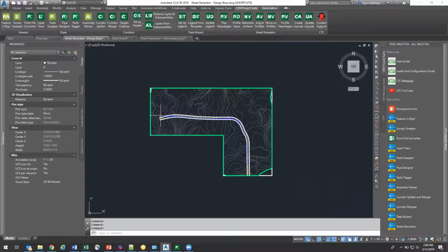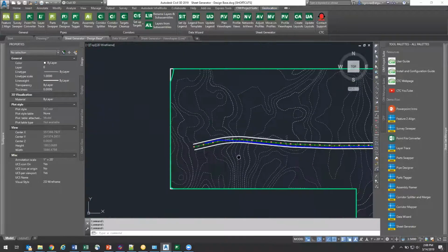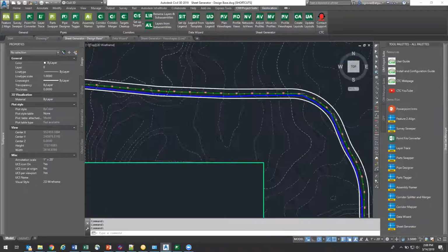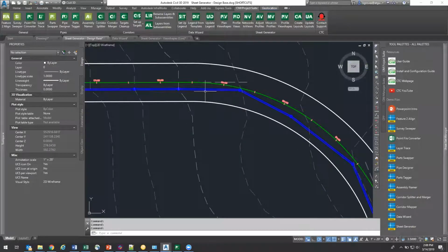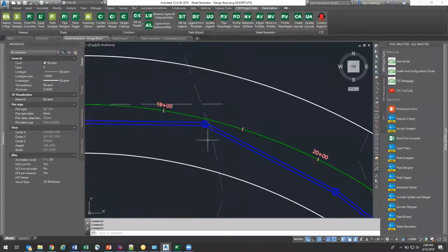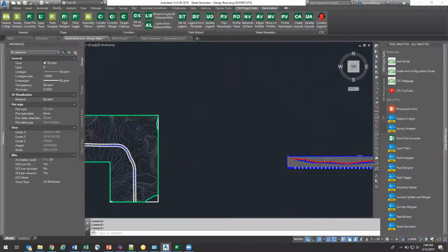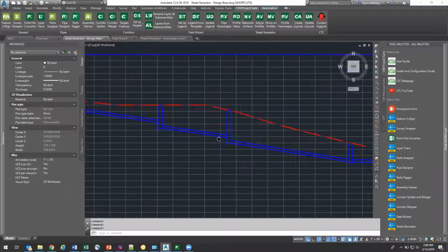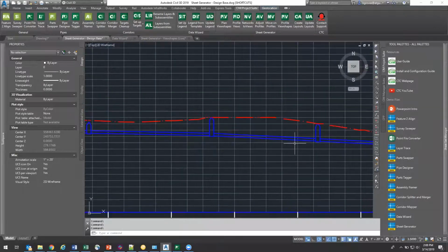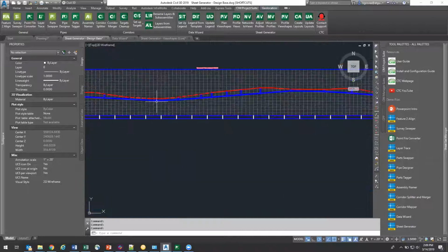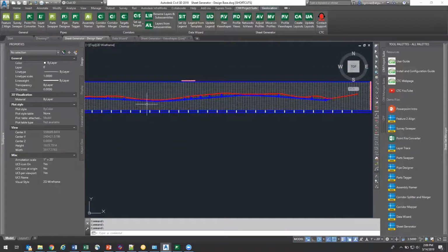We're starting with just a Civil 3D file. We've got our surface. This is adding in some sanitary or some storm along this roadway. We're not really cutting into the road at all. We're not redesigning this roadway. We're just going to add in this sanitary along it and bring our grades all back to existing. And I can see over here in my profile view, I've got my existing surface and my pipe network. Everything is running clean down to about station 1470, and then we're running back uphill a little ways.